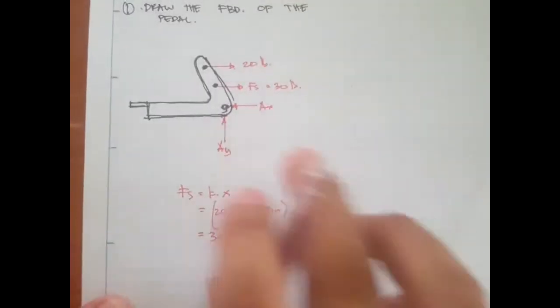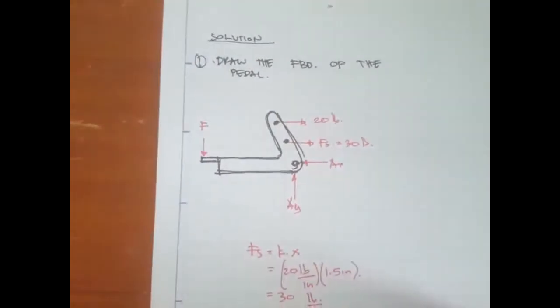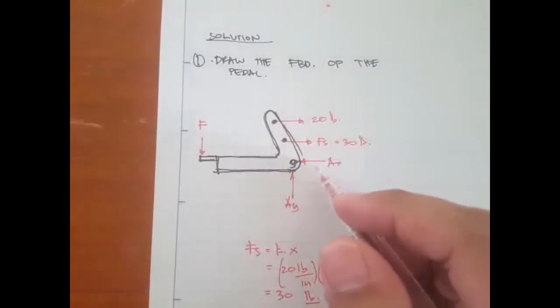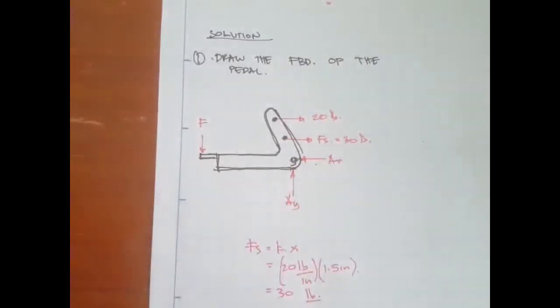We have AY, AX, and right here our unknown force. Looking at the problem, we have three unknowns and three equations of equilibrium, and therefore the problem is determinate.